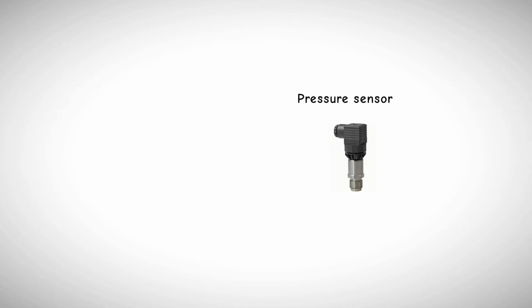Another common analog signal format used in industrial sensors is the 4 to 20 milliamp current loop. This robust signaling method offers several advantages. The 4 milliamp baseline serves as a live zero, allowing fault detection, while the 20 milliamp represents full scale.